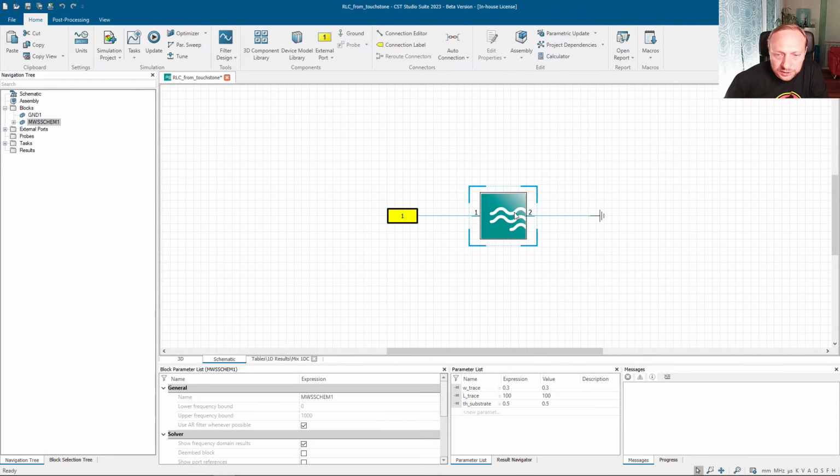So simply inside this block is again the S parameters. So the 3D solver passes on the S parameters to my circuit. And what I do is I just simply now short the other side. So what does the setup mean? This port is a source, or now for the S parameter calculation, it's a 50 ohm port at the one side and a short on the other side.